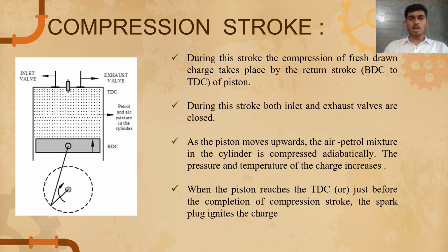So coming next, the compression stroke. During this stroke, the fresh charges are compressed due to the movement of piston from bottom dead center to top dead center. So this piston will move from bottom dead center to top dead center so that the charges present between the cylinder walls and the piston will be compressed. And during this stroke, the inlet valve and exhaust valve will be closed.